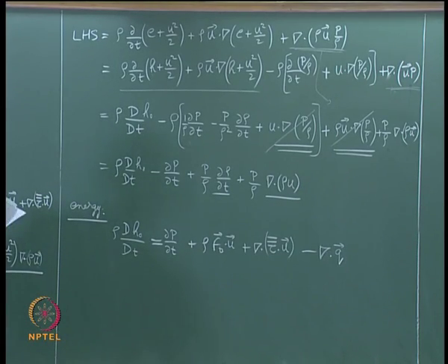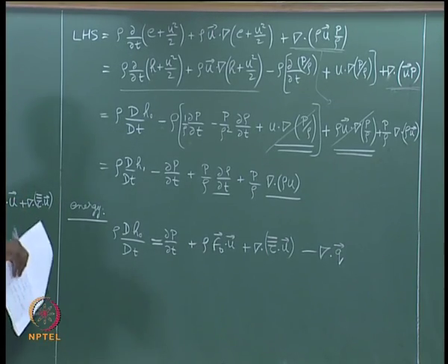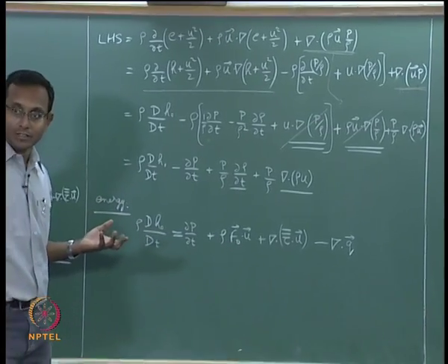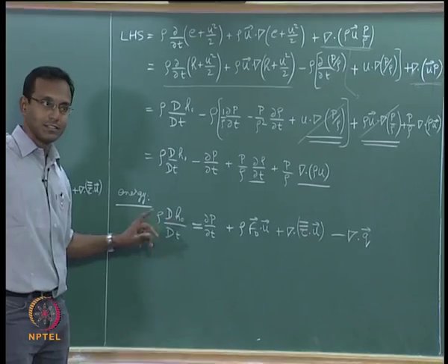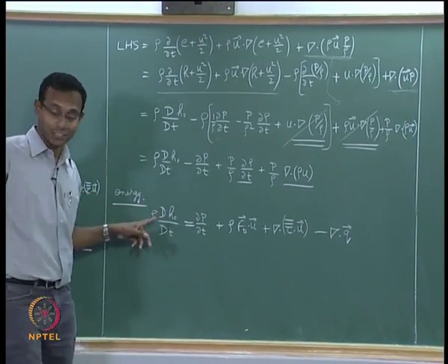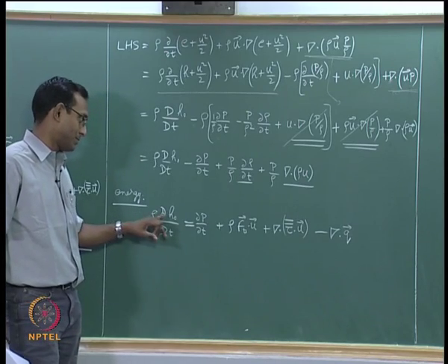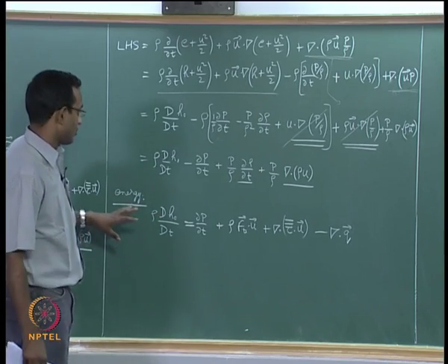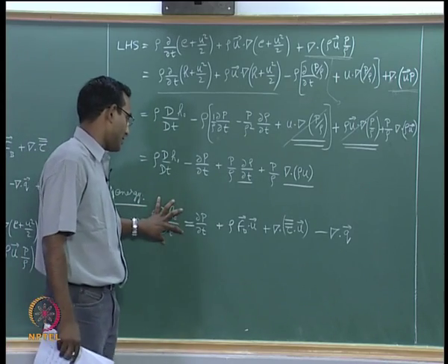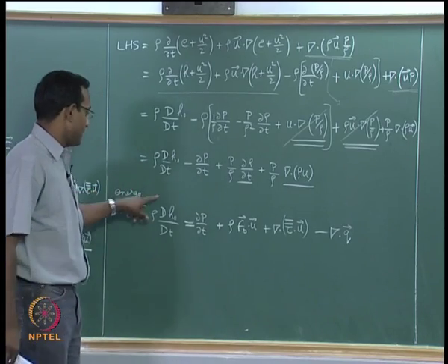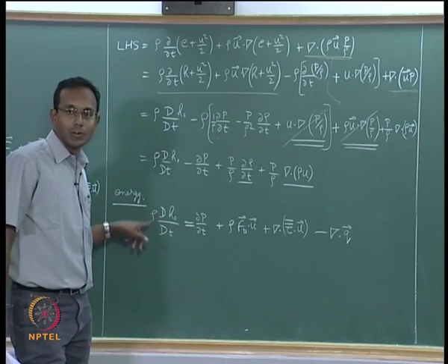We won't do any more changes to this. This gives you some more physical feeling. Okay. All this time we said total enthalpy is the net energy content of the fluid. This includes kinetic energy as well as internal energy, thermal energy including the pressure energy. It is having all forms of energy, thermal energy, pressure energy and kinetic energy. Complete set is inside this. So, this is the net content of energy in that particular fluid element. Now, we want to see the change in that particular quantity.